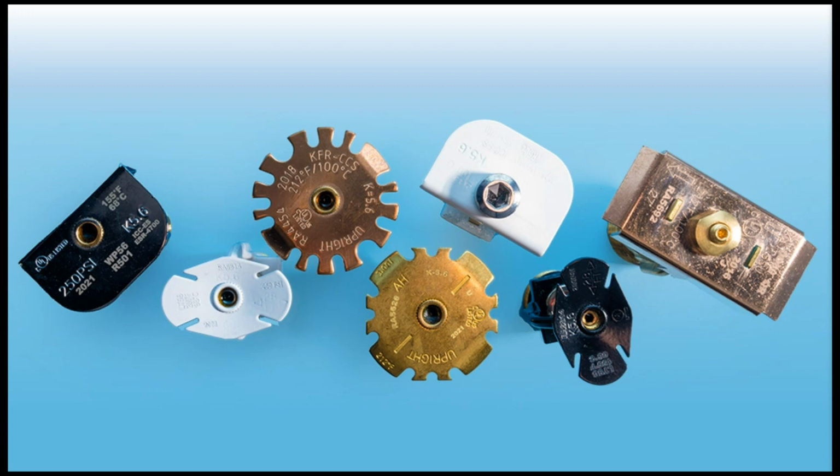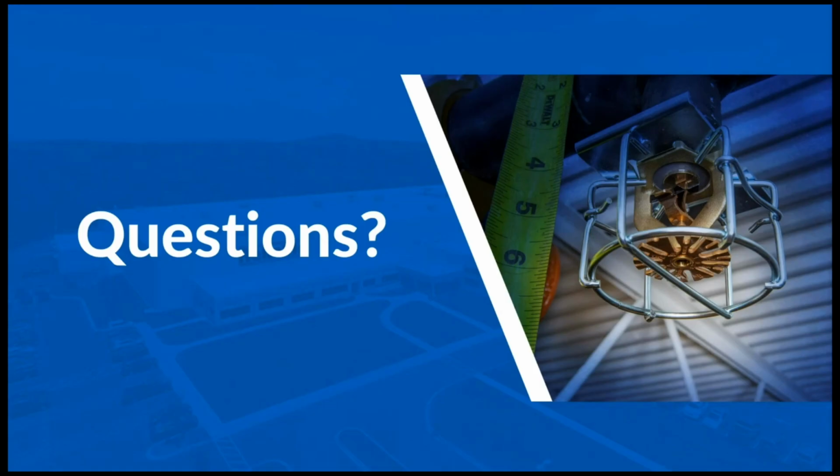Only one of those sprinklers, however, was actually required for you to be used according to NFPA standards, and that's going to be that concealed combustible space sprinkler. Everything else is really up to you as an engineering professional, sprinkler contractor, or AHJ to allow or approve their use. So with that being said, we'll handle some questions if we got them.